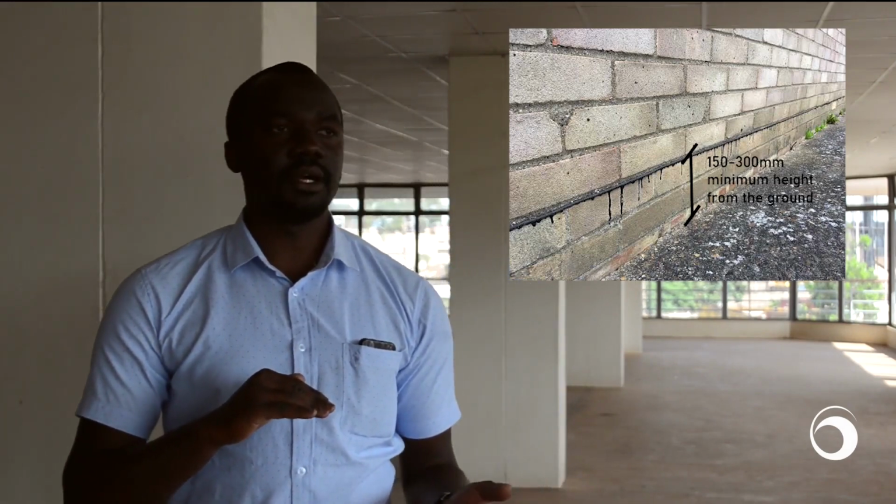That would mean that the wall or the slab doesn't have sufficient distance from the ground. It's normally advised that you provide at least 150 millimeters or 200 or 300 if you can between the floor and the existing ground where you will have splashback to prevent any such issues. However, in the case where it is as a result of lacking a damp-proof membrane or a cause thereof, you'd need to provide remedial methods.